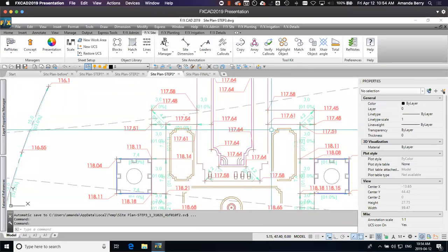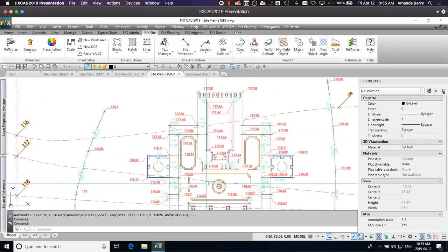I decided the best solution in this case, and there's always multiple solutions to a problem, would probably be to have a little bit of a swale in here and then a drainage trench just through here with maybe a grate over top so that it could just flow out here. I decided that would probably be the cheapest and most economical option instead of having it drain in here and put a little capture drain or catch basin even and pipe it out there. I decided a little channel drain was probably all that this needed to drain these two areas out, and the rest of it could sheet drain.